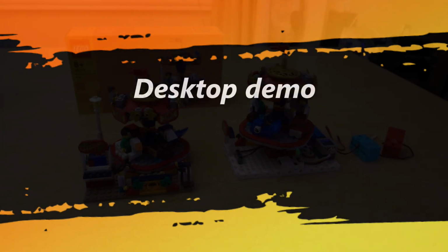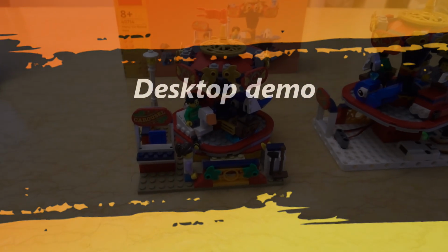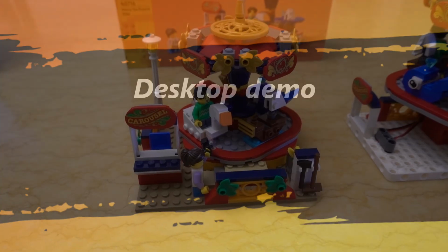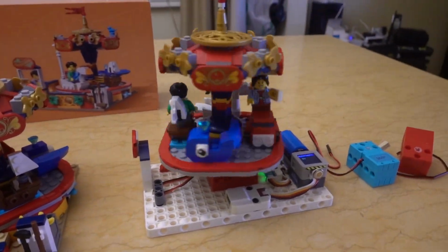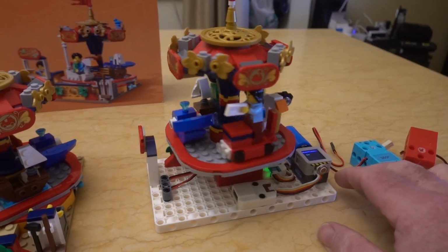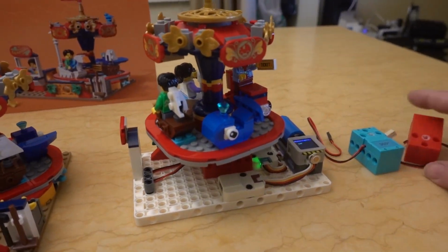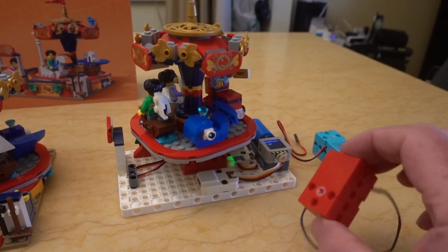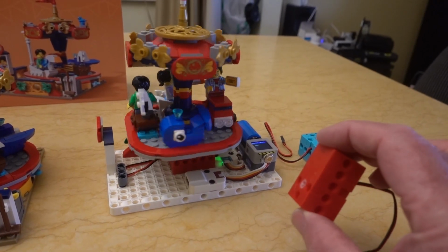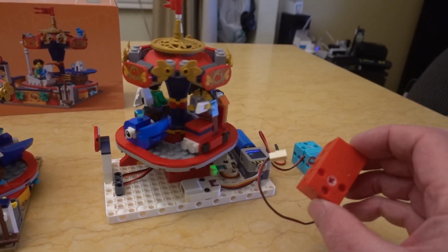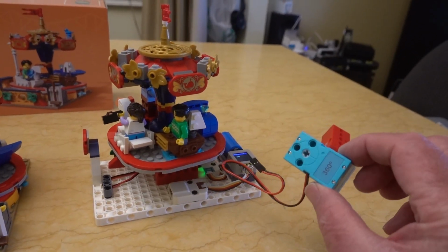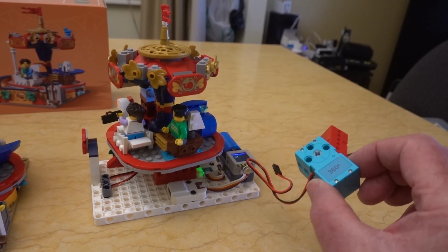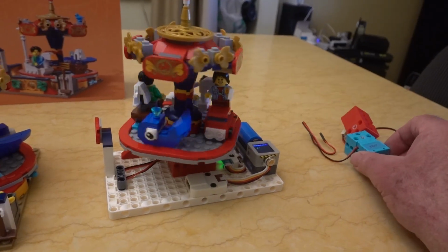In this project, we take the Lego merry-go-round or carousel, and it comes configured like this. We're going to add an electric motor to it and a motor drive. So the motor is this one here. It can go up to 2 kg/cm torque, or alternatively, you can put on one which is geared down for a slower speed.